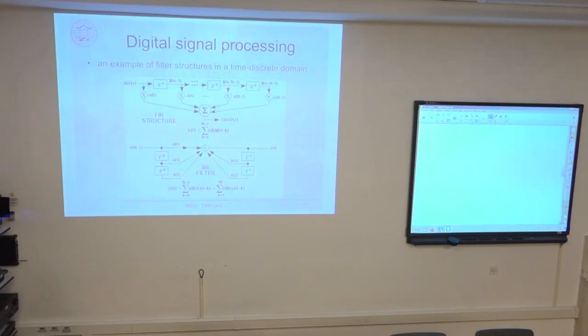So it takes the current input signal value and all preceding samples up to time step n minus capital N minus 1 and takes a weighted sum of these samples. And this A of k are weights that I use to compute this weighted sum, and these are constants. This A of k are stored in memory. These are filter coefficients.